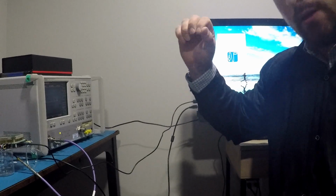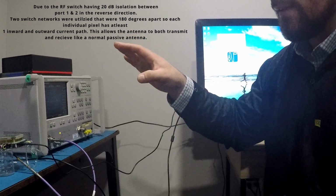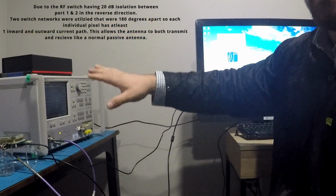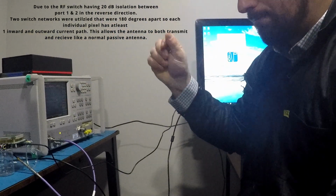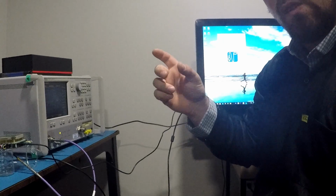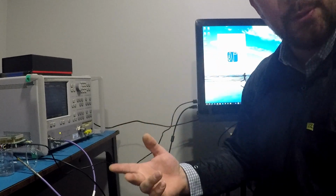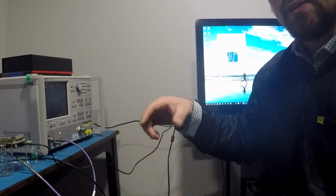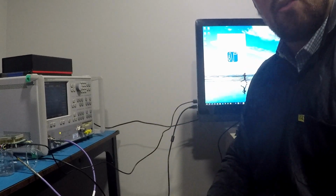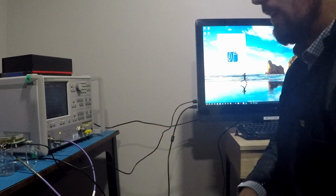I don't know if I mentioned in the intro, there is 2 separate logic boards, both for transmit and receive. So this antenna can transmit and receive at the same time. You'll see it when we do the next test after we build the data set for the AI right now. So from pixel to pixel, the most amount of loss it'll experience is about 2 dB, but that can be cut down by taking multiple paths. Since we have two logics in there, it's controlling separate switches, so we can create multiple current paths through each of the pixels. So that's pretty neat. Just if people are wondering why there's 2 USB cords.